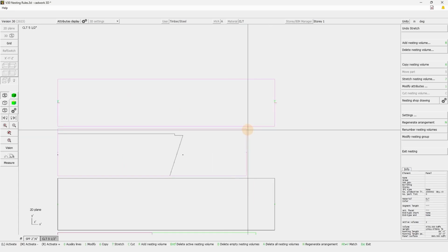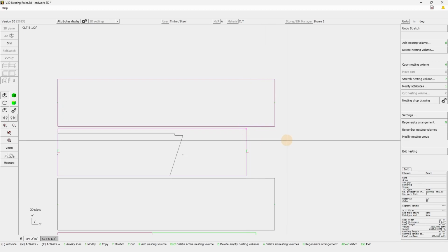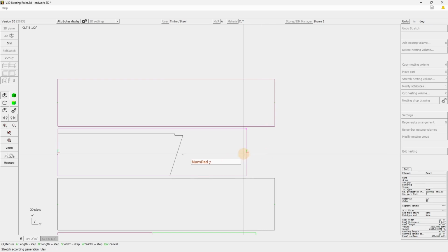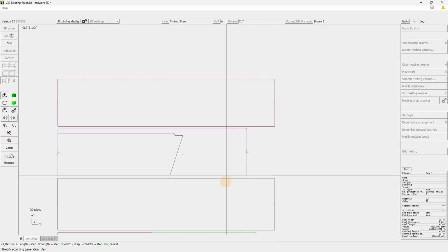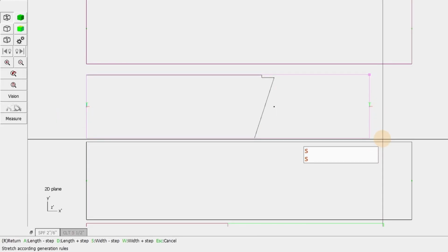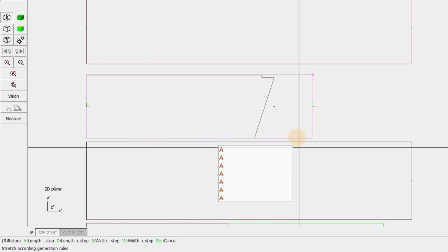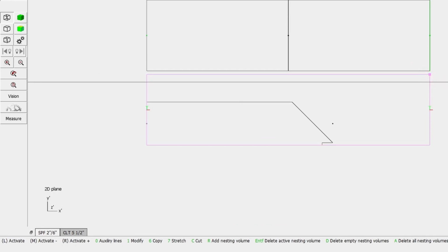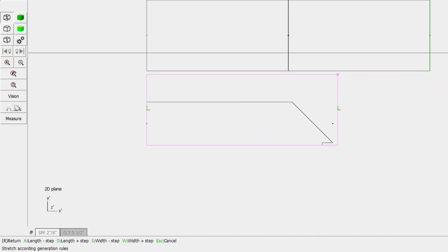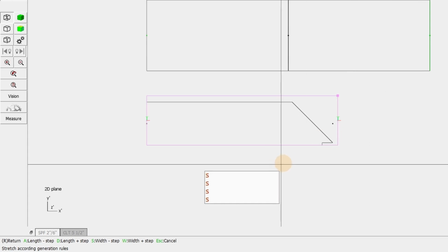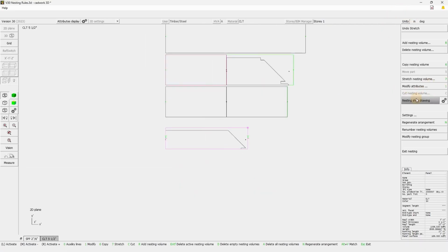The same as in Cadwork 3D, when you stretch volume, the location of the anchor point is really important. This is the point that will actually move. Since here we move along the length or the width, your panel will actually change format based on that specific node. As you can see here, top right corner, meaning that the panel will be fixed on its bottom left corner.